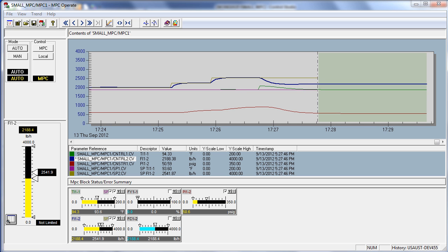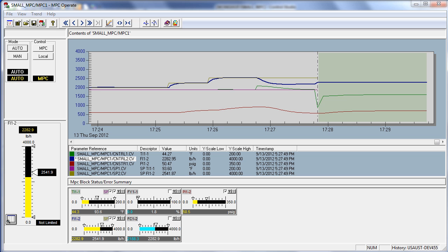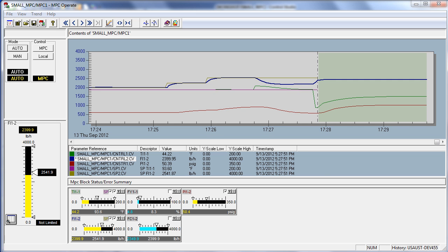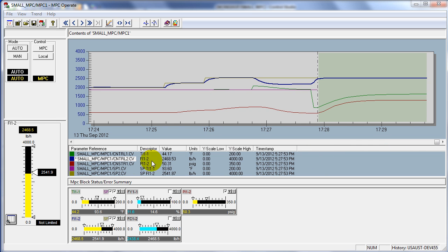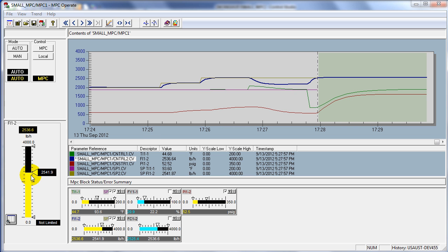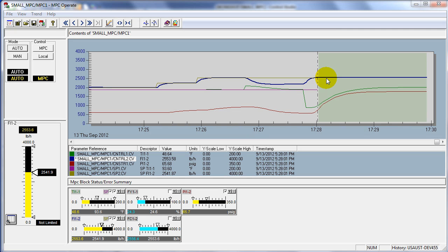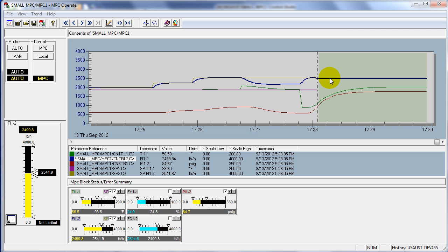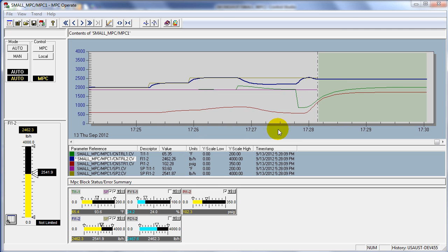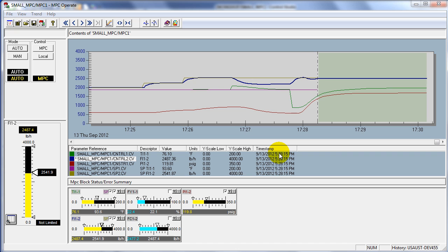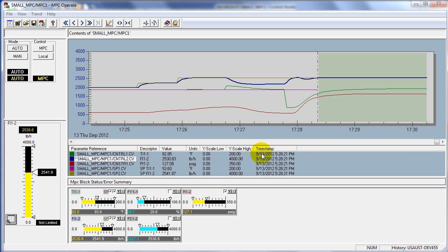Under this condition, if the cooling capacity suddenly becomes greater and the temperature drops as is shown here, then automatically MPC raises the feed rate back up to what the operator requested, because now there's plenty of cooling capacity to achieve the target set point. As it raises that up, the temperature control done by MPC automatically regulates the cooling valve to get us right at temperature set point.